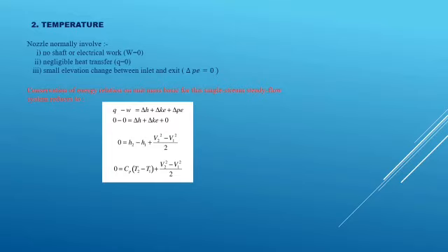Secondly, we will talk about temperature. Okay, nozzle normally involves no shaft or electrical work, so W equal to 0. Secondly, negligible heat transfer, which is Q equal to 0. And small elevation change between inlet and exit, which is potential energy, is equal to 0 also.